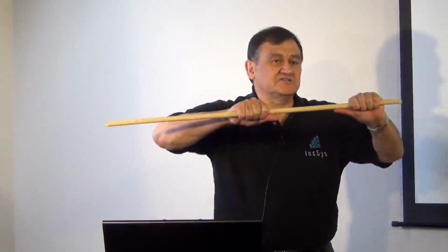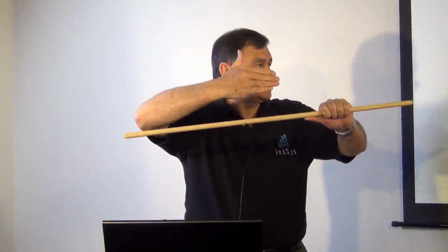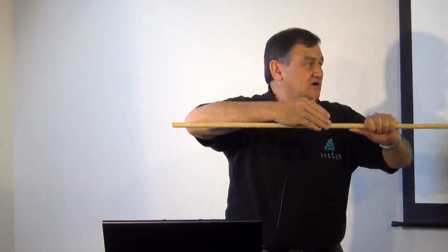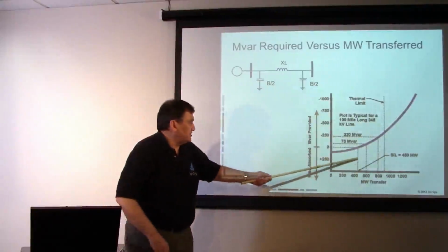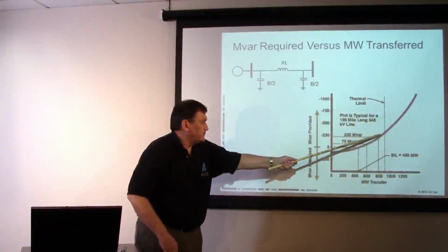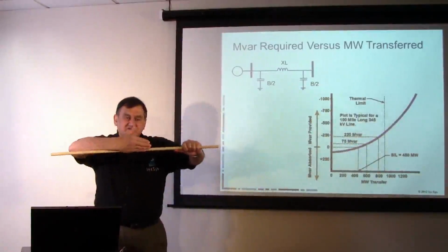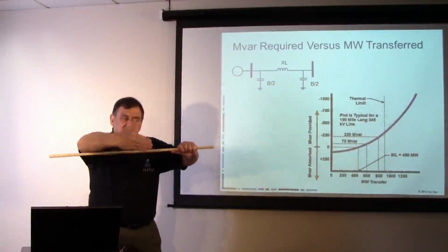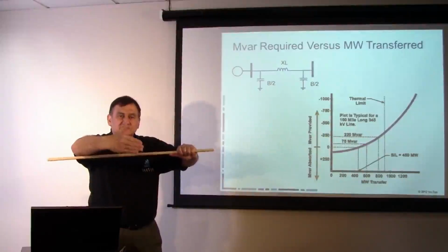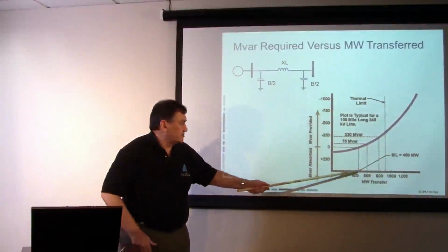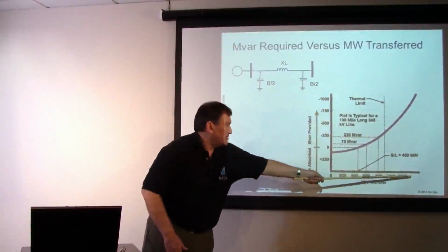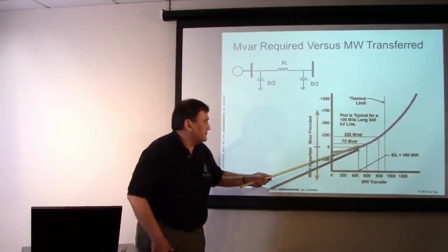Especially when you have contingencies. Imagine we have two lines in parallel. Let's say this line is at twice the surge impedance loading, so it would be, say, at 900. But then that line trips out of service. So we're taking that other line, and it could go to 4 times the surge impedance loading. So look, we could go from here all the way up to here.